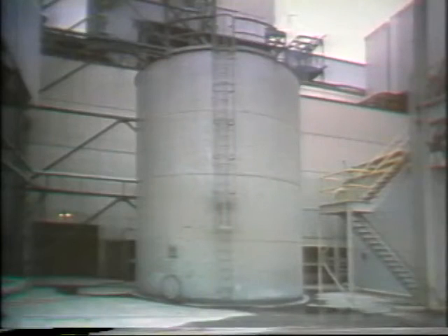One place where the measurement of flow is important is when fluid is transferred from one tank to another. If you need to fill this 80,000-gallon storage tank with water, you'll want to know how long it will take. To find this out, you need to know the flow rate at which the water is pumped. Let's say this pump, which fills the tank, is operating at its rated capacity of 80 gallons per minute. How long will it take to fill the tank?